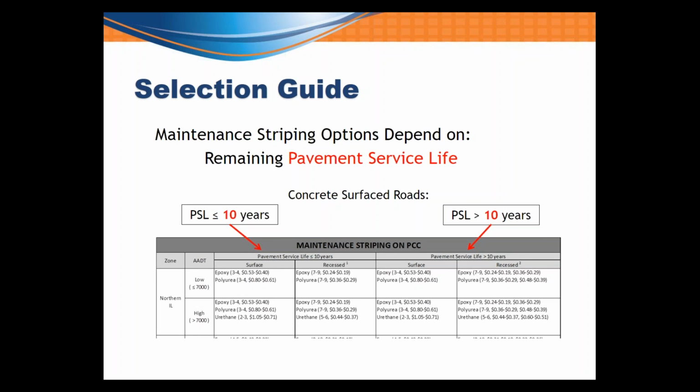We also do the same for maintenance striping on concrete surfaces. However, the cutoff between the different tables is based on a pavement service life of 10 years rather than the 5 years that we use for asphalt.